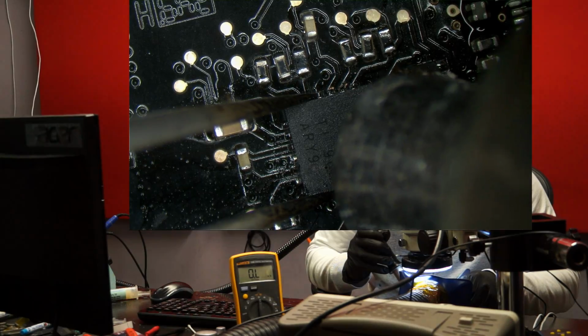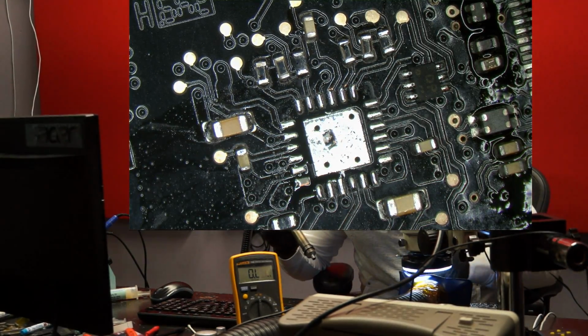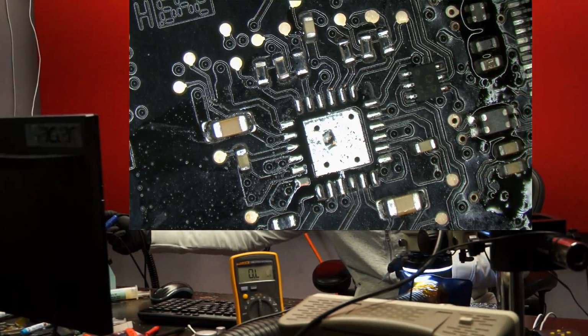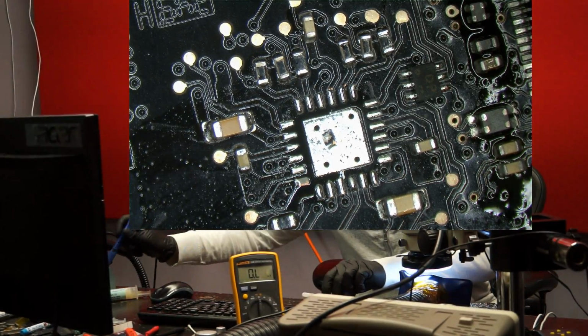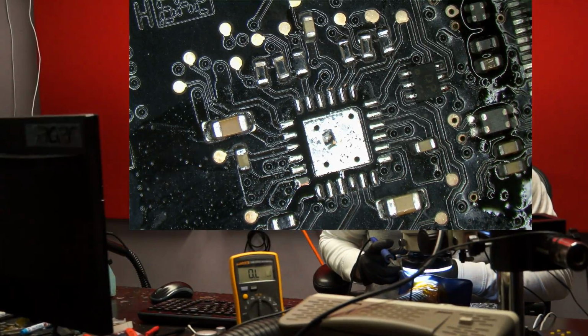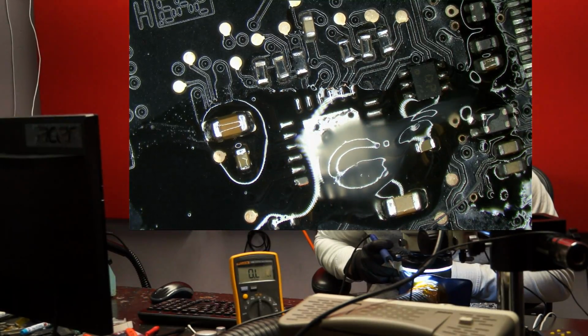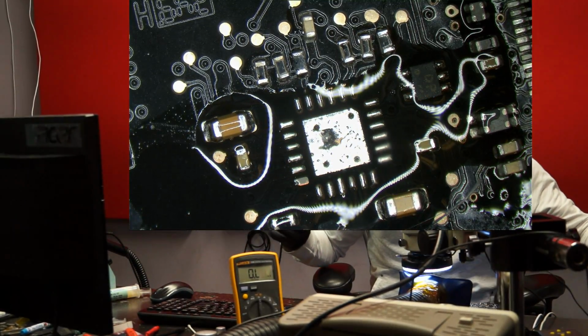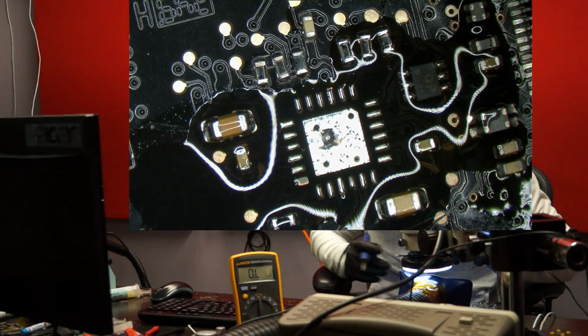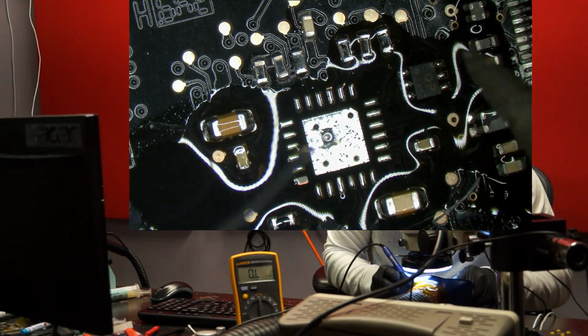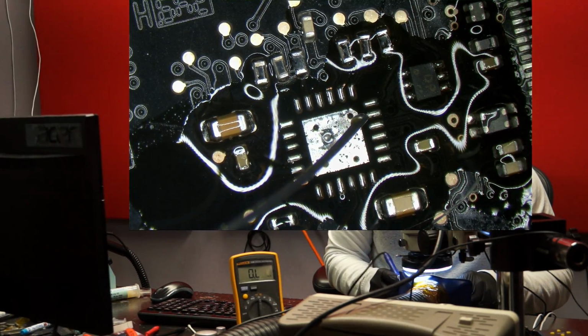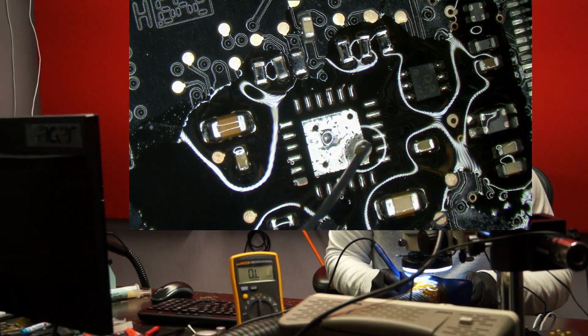Okay. Take the chip off the board. A lot of people get the orientation of this chip wrong, so what I do is I actually solder it onto my table. That's why my desk looks like shit. But I don't care, because my chips are always soldered on the right way, since I solder the component to the desk. While it's still hot, I shove it onto the table. At the end of the day, I knock all that stuff off and I clean the desk.